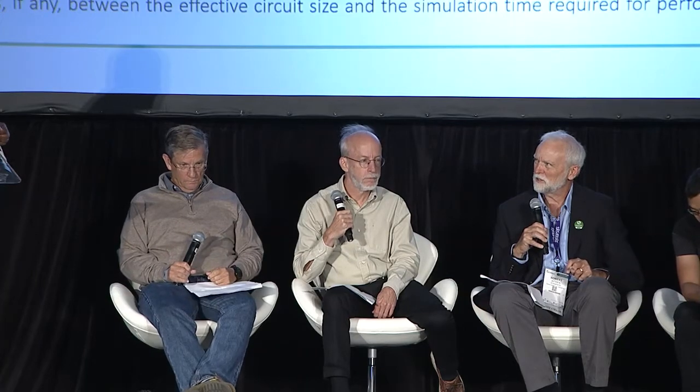Okay, but if you didn't have any silicon data and you said, well, this is going to vary, I'm going to just stick my finger in the air and declare this will vary by 5% and construct a model that way and see what happens, would that work? That is definitely one way of doing it. So, even if you don't have silicon data for your rings, you typically have a lot of data for your line width variation as you fabricate these waveguides.